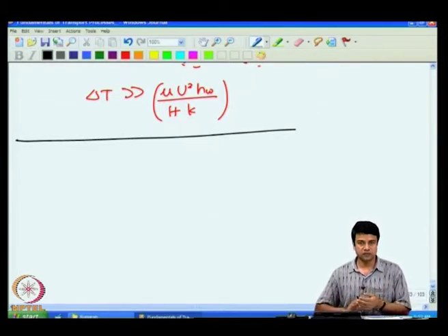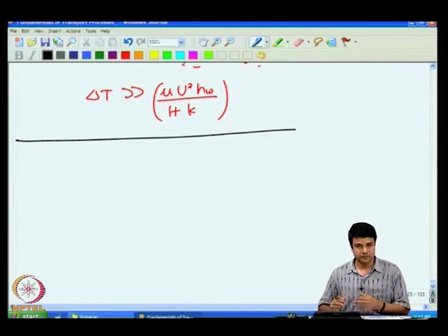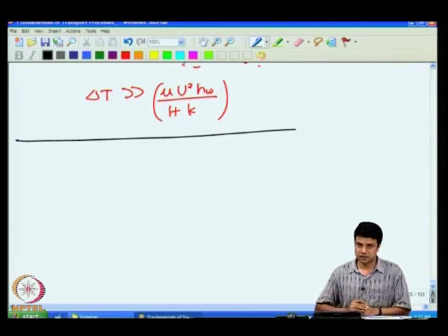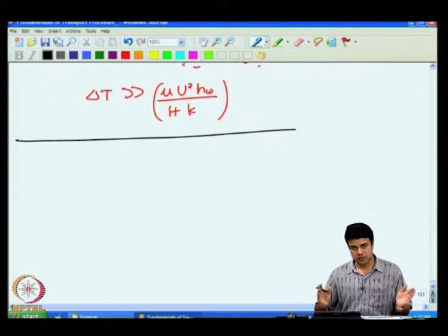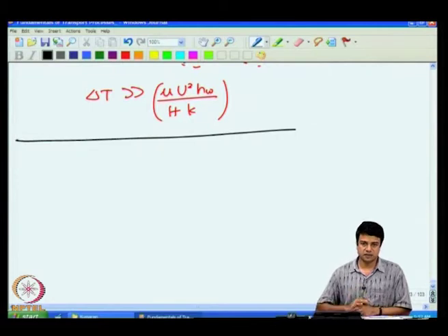One is where there is a body force which tends to force the fluid, and the other is where there is a pressure difference across the ends which results in a pressure gradient along the tube. I showed you that the effect of the pressure gradient is effectively equivalent to a body force acting on the fluid. And then we solved a problem here of the heat generated due to the viscous flow within the channel.